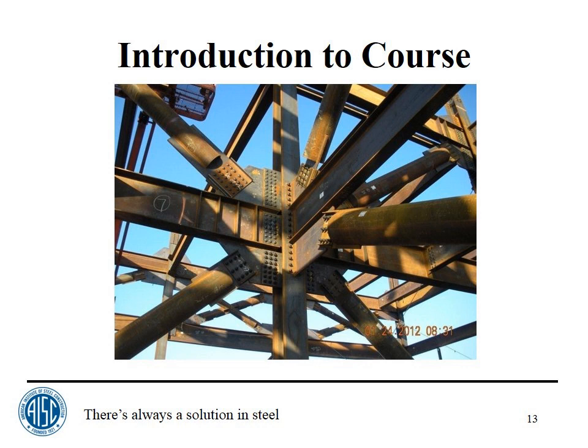But I don't see any big advantage to using it in 9 out of 10 of those, because we basically use a wraparound gusset. You end up with a cutout in the corner of the gusset to get around a column, because usually these connections are going to be horizontal beams framing to column flanges and column webs. But there isn't any reason why you couldn't use it. Well, we'll have to talk about that in one of these sessions. Maybe that'll be in session 8. We'll maybe do some wraparound gussets. But I've never really used the uniform force method for a horizontal brace, but there's no reason why you couldn't.